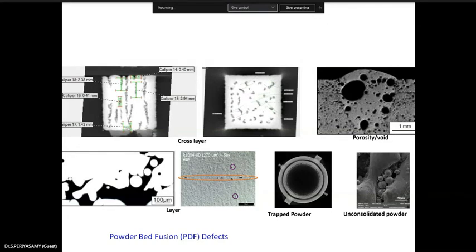the feed rate, then the timing, etc. Flow rate, everything will be given. Then another one, titanium 6 aluminum 4 vanadium, extra low interstitial: you have to use ASTM F3001, and for a nickel alloy with this standard you have to go for F3055. N is not applicable, S is surface sensitive, then I is internal or through thickness. On the internal side you can get the details, then Y is applicable.